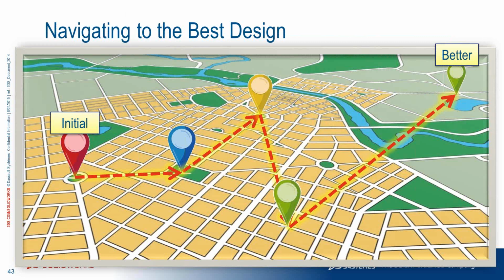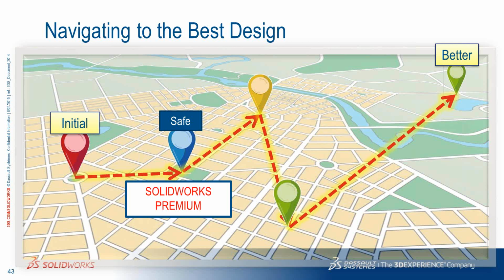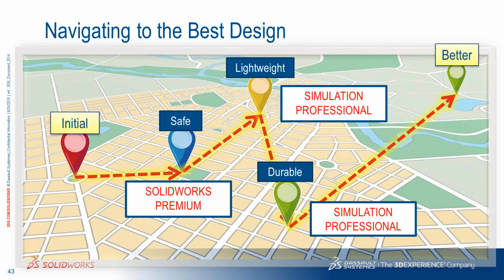But what this wheel rim demonstration hopefully showed you was how we could take an initial design to a better design. We tested initially for strength, which is making sure that the operating loads are safe, and that you can do today with SolidWorks Premium if you have that particular package. But then we took the next step in the process to lightweight the design using Simulation Professional, and also make sure that it's durable enough, that it's going to last X number of cycles, so making sure that it's going to last 20 rallies or 40 rallies and so on.